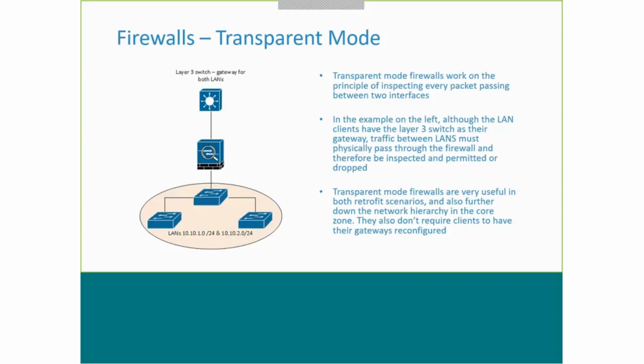Okay. So in terms of retrofit, you could add a firewall. Do they have learning modes? Some do, yes. I know in the Hirschmann world they make it quite easy for you, or at least easier. They do have a learning mode. It's a transparent device when you put it in learning mode. It passes all traffic through, it doesn't filter anything, but while it's doing that, it's inspecting all the connections. After a number of hours, a number of days, or however long it may be, you've got a big list of rules, almost a baseline of the traffic that's passing through it.